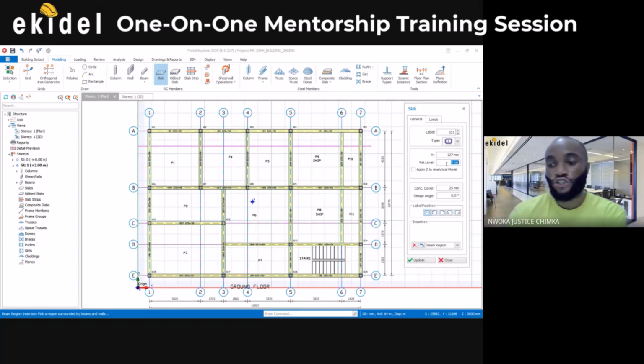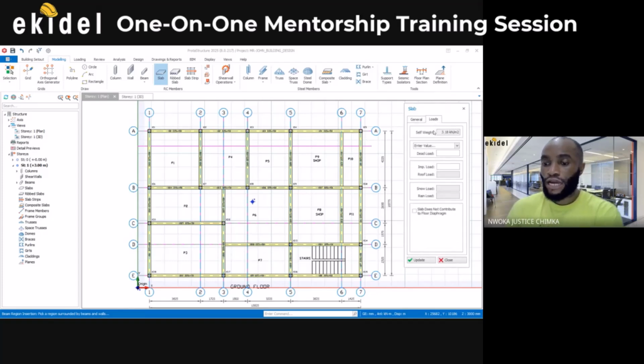Yeah, so this is used to separate or to show difference in the slab level. That way you can use this level. Okay. Then you now come here that says loads. Under loads, automatically once you put in your height, it will give you your self weight, because the depth of the slab times the density of concrete will give you the self weight.